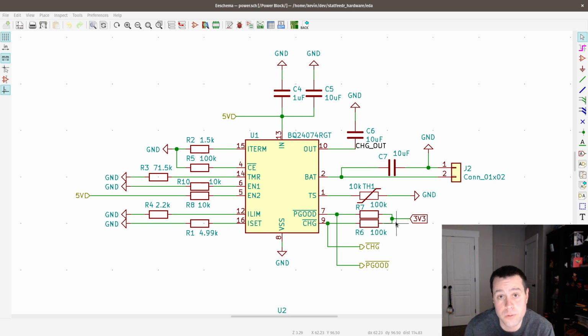That's what a lot of the parts will call it, a battery fuel gauge, LiPo battery fuel gauge. That is going to require an increase in my bill of materials. I have to have an extra chip. I think a lot of them don't require a lot of supporting circuitry, but at minimum, probably an extra resistor and capacitor here and there,